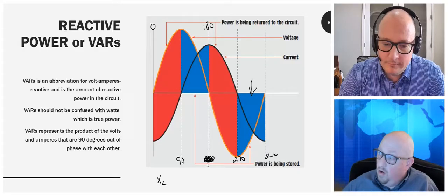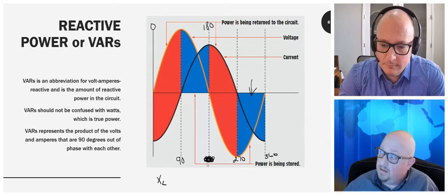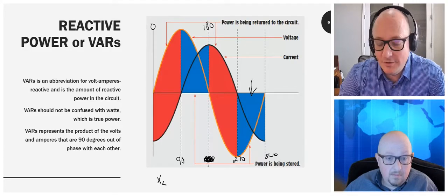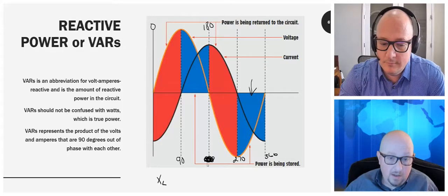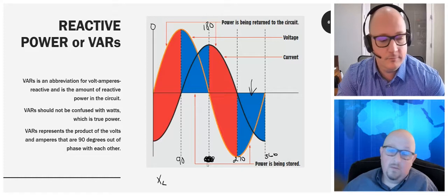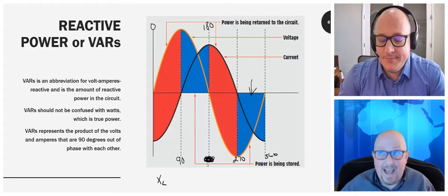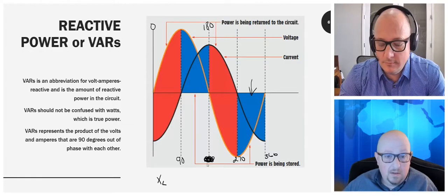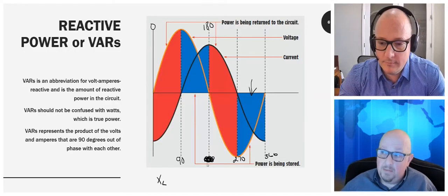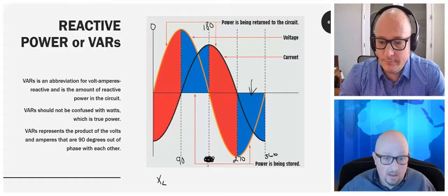So ultimately, what all this does is it creates magnetic fields that act like resistance, in the form of opposition to current flow. Therefore it allows me to lower my current, because it acts like resistance, the same as a light bulb doesn't trip a breaker. My transformer won't trip a breaker because it has some type of impedance lowering the current. Yeah, overall circuit impedance.